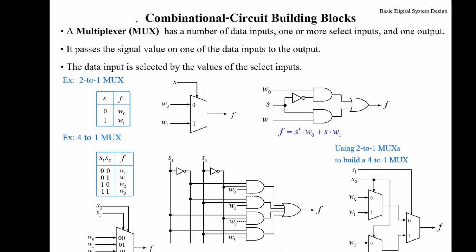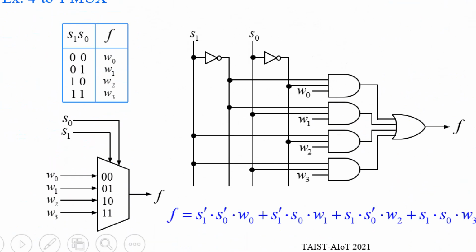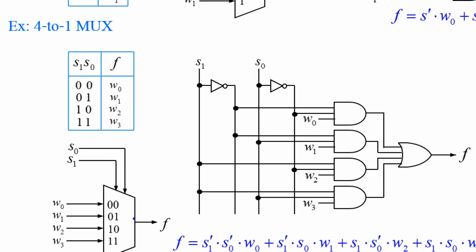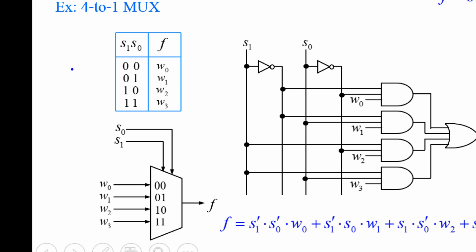It's a multiplexer. And this one just shows you an example of a 4-to-1 multiplexer, namely 4 inputs. That means you must use 2 bits of selector signal. Namely, if the selector signal is 00, the input at 00 position will go to the output.